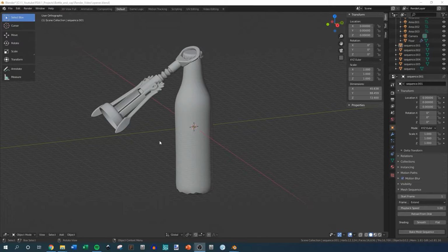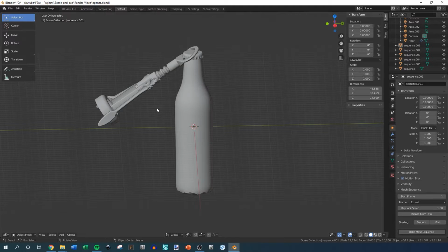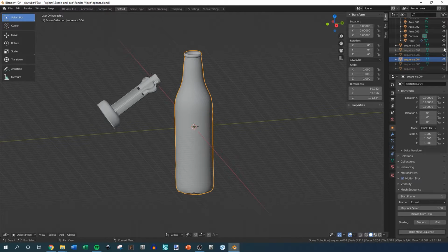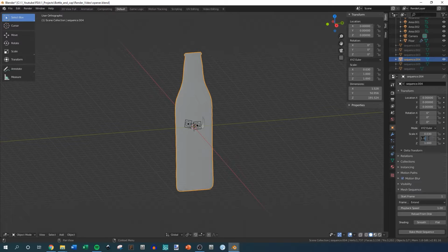Once you get all of your objects imported, what we're going to do is scale everything down. You want to make sure you're over in this orange square tab again. Unfortunately, you can't scale everything down at one time, so you have to do it one by one. If you left click, you can go down over here to scale and mess around with what is the correct size. I suggest, if you're going to figure out the right size, taking something like the bottle or the main feature, hiding everything else, and looking at a scale factor. I know this is going to be 0.03, and that's an X, and you're going to have to do this for all of them.